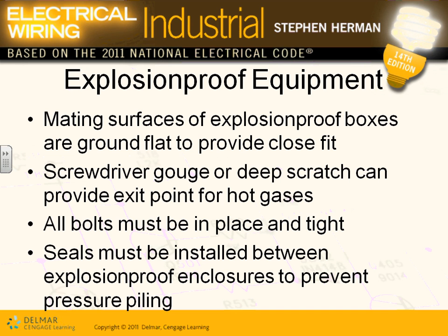All bolts must be placed in place and tight. This is mostly for the electrician, workman-like manner when you go there. Long story short, what I want to summarize to you guys: if you're a project manager on an explosion-proof job, pay a lot of attention to the actual physical installation of this job. It's not like just a J box, I'm going to go put it there. So pay a lot of attention to the workman-like manner.